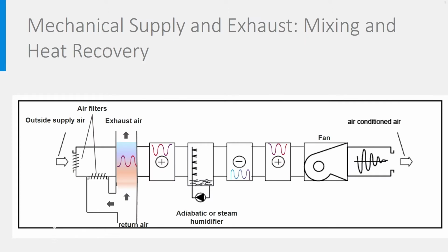Let's look first at the case when there is a return pipe, exhausting the polluted air from the rooms. In general, during the heating season, this air is warmer than the outdoor air, giving possibilities for heat recovery. During the cooling season, it may be that the return air is colder than the supply air, and heat recovery, in fact cold recovery, can then also be applied.